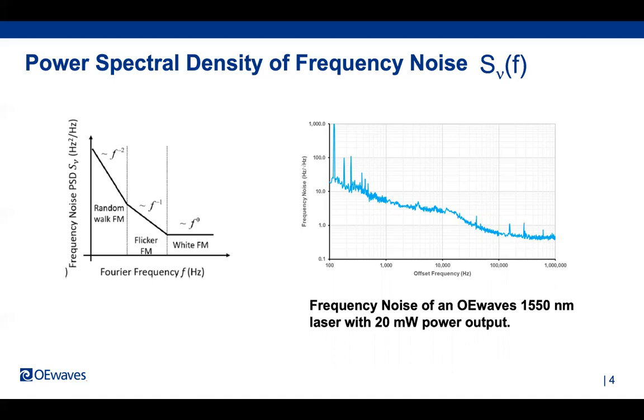For example, when we talk about the line width of the laser, typically we're talking about this wide frequency noise region, which is called white because it doesn't change as the frequency changes; it's flat. But when you go to these other regions, they have different slopes, and each one of these slopes is indicative of some underlying phenomenology in the laser operation, including, importantly, some technical noise due to, for example, vibration or temperature, etc.